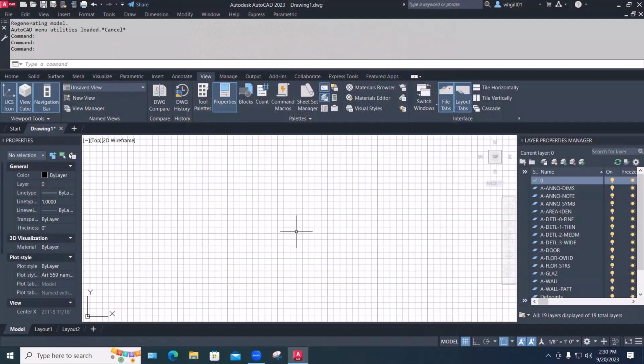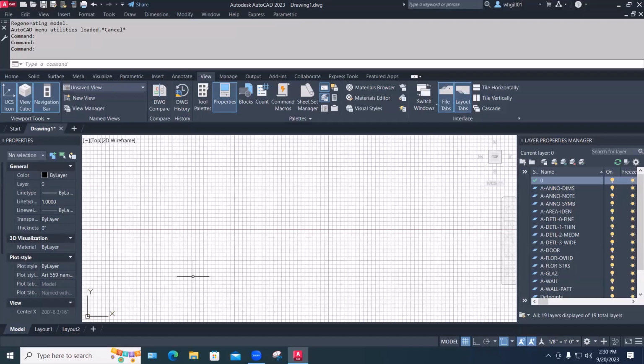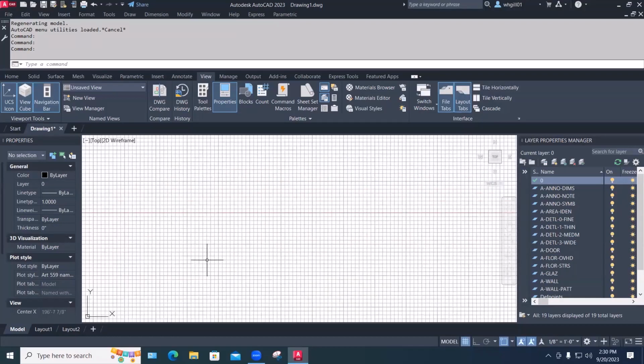First, I'm going to draw a 1-inch radius circle at the origin of the drawing, just so I know where that is. And a couple things about this icon here of the coordinate system is it's sort of floating right now. It's not actually staying on the actual 0, 0 origin of the drawing. It's just sort of indicating which direction X and Y are.